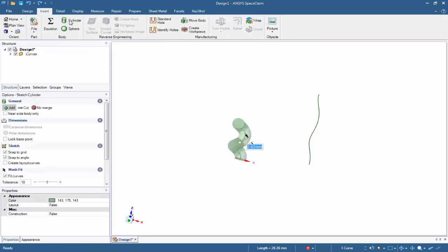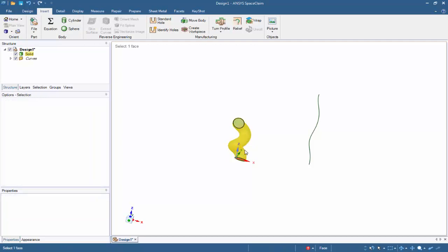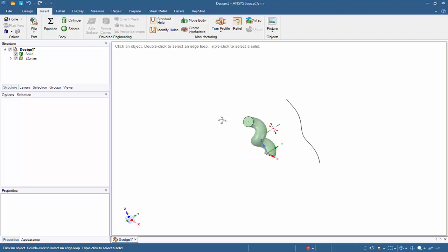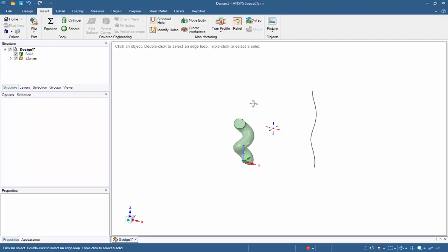Once you select it, notice that your cursor is immediately placed onto the cylindrical preview. Move your mouse to the right or to the left to adjust the size of the cylinder. Again, do this slowly because if you go too far, it might produce some unexpected behavior. When you're satisfied with the preview, or if you type in a value, go ahead and click on your mouse or hit Enter. You'll now notice a cylinder has been fit onto the actual curve.